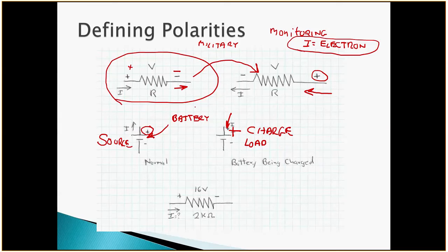Any questions over that? Any concerns over that? Those defined polarities are going to be important for us going throughout all 5 classes of electricity. So down below, we have a real small example here where I've got current entering into a resistor. There's my positive terminal. Current always enters the positive terminal of a resistor.